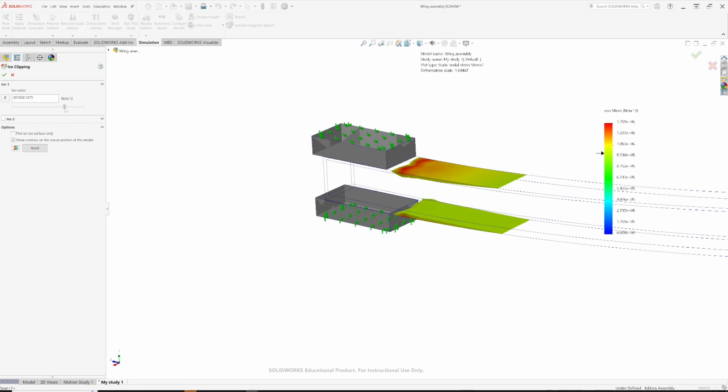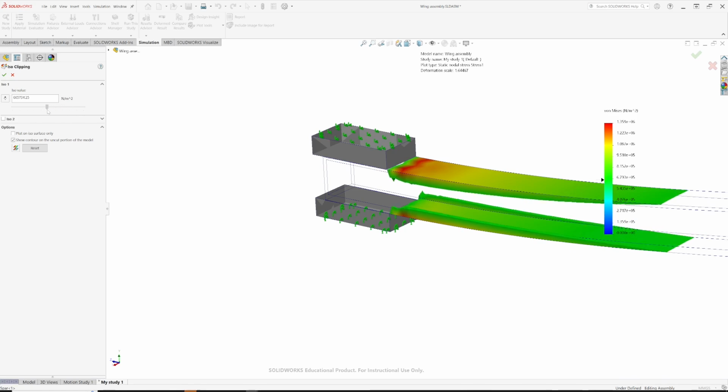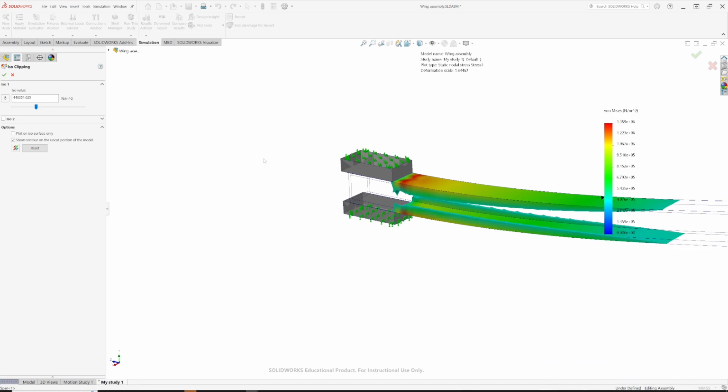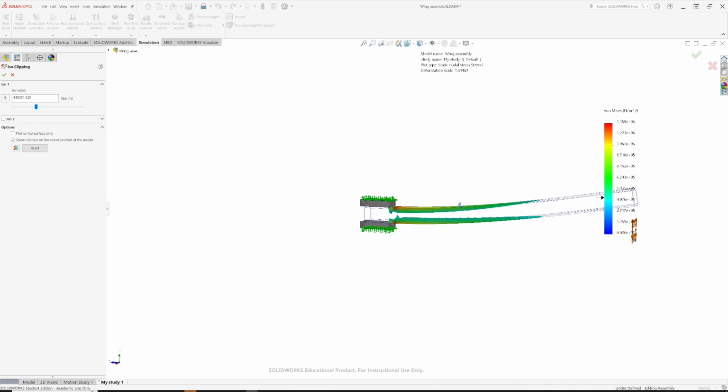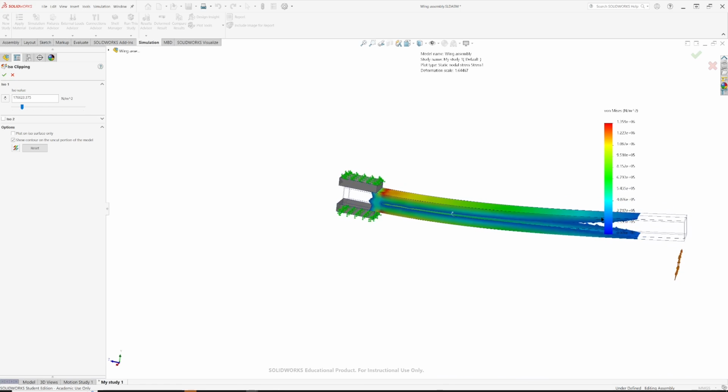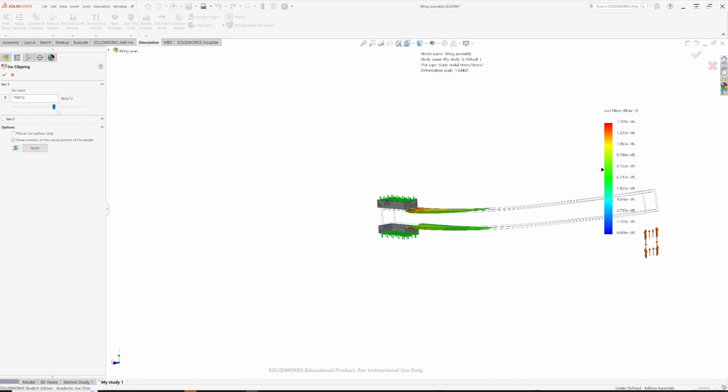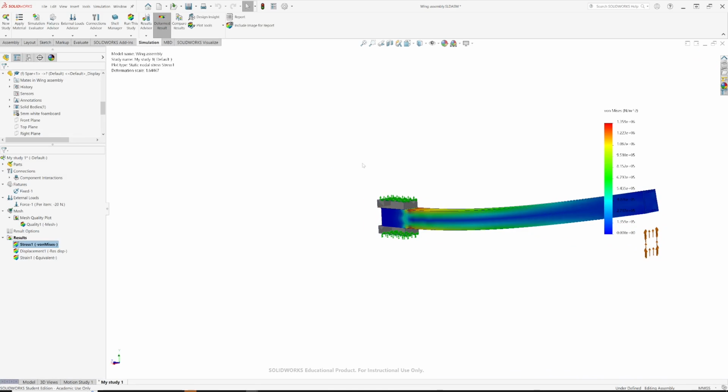And if we reduce that contour, we can gradually see more and more of the beam, the stress levels getting lower and lower. So in some ways, this kind of closed peg sort of shape, you could call this sort of structural optimization, but this is where the material is being loaded, so this is where you need to place the material in the beam. It's never quite as simple as that because you've got to hold the thing together, but this just gives you a visual indication of that. Okay, that's good. Let's actually turn off the clipping.